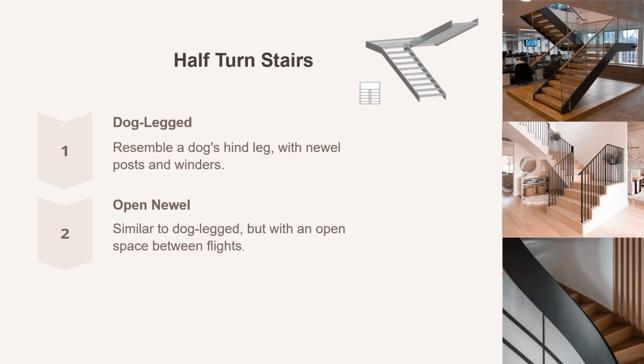The additional width is required between the two stairs. The space between the two strings may vary from 15 cm minimum to 100 cm. When the space left is more, a small flight containing 2 to 3 steps may be introduced at the turn between the two quarter space landings, as shown in the figure. Otherwise, for a small width, a half space landing may be provided, also shown in the figure.